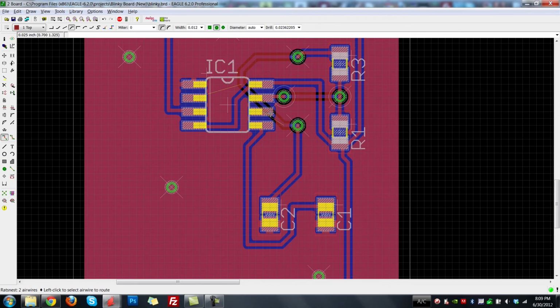We need to connect to this pad, for example. So let's do that. We have the top selected, click the pad, and we'll just go ahead and route it over to our via. I'll change the bend method, and perfect. Click rat's nest, and we can see it made its way through the ground port over to that via. We have one more connection.